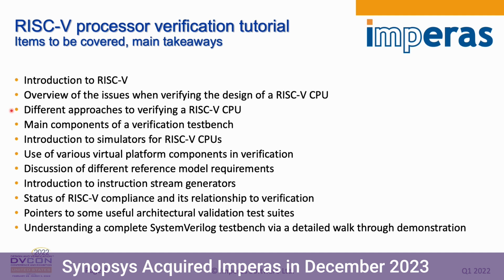We're then going to drill down into different components in verification test benches, introduce some of the simulators available, both free and commercial. Then we're going to talk about the different components that you might need in your virtual platforms or your simulation for your verification. We're going to talk about the reference models that are available out there and the capabilities that are needed, introduce tests and stream generators, instruction stream generators, talk a little bit about verification in relationship to compliance, and provide a detailed walkthrough of a SystemVerilog test bench verifying an open source core.